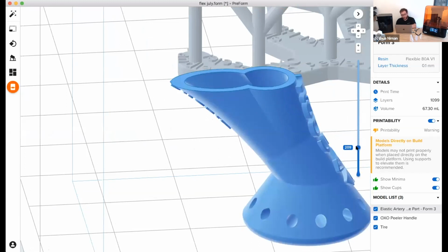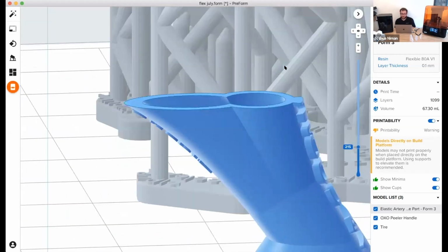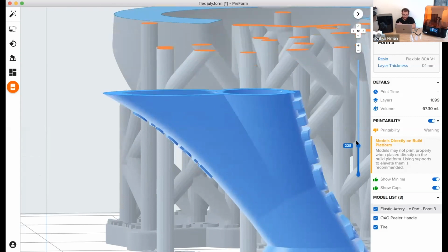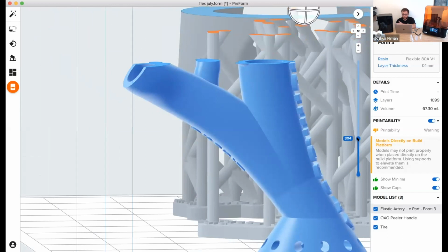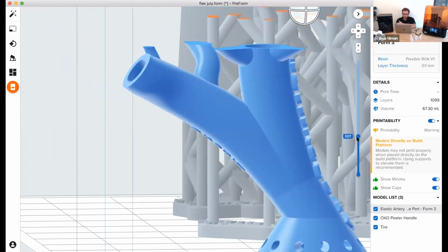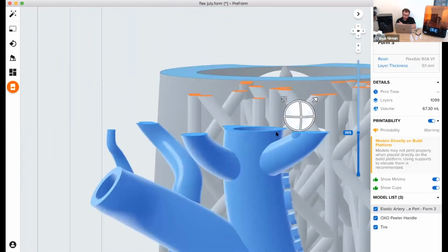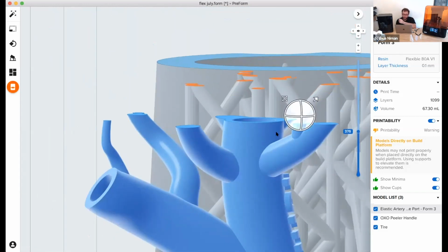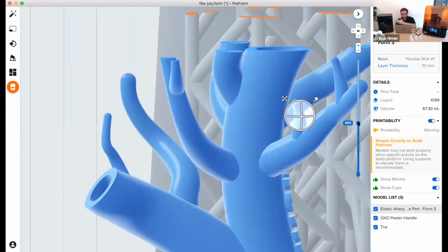And so slicing up through it, anytime I'm doing that, I'm always looking for overhangs that are coming out of nowhere and making a really fragile surface. And you can see this is an intelligently designed part, right? Because every time we go up through these layers, you have these overhangs that look dramatic, but the actual angles that they begin at are mild enough, and they're all within our design guides and the things that you can read on our website about this, that we don't need supports here. And yeah, they're fragile, and yeah, they're poking off, but they're all moving upward relative to the build platform.